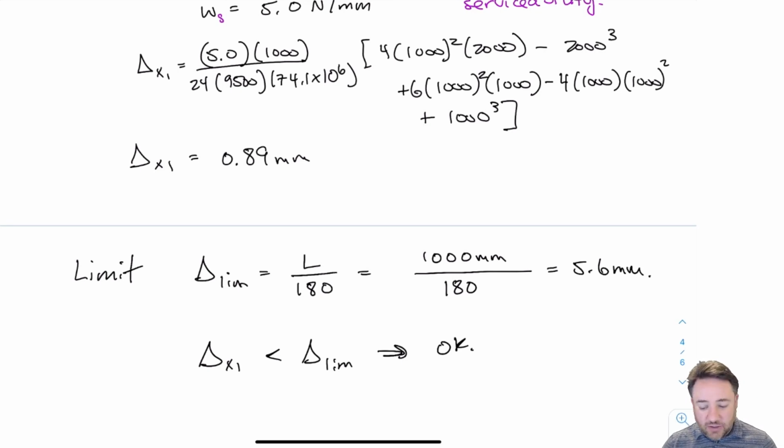So I'm fine. Okay, so in this problem, I looked at a sample lumber beam design. We calculated our size effect, we calculated our S, we found our strength, we looked at our unit strength, we looked at KL, we had to calculate KL for 2 different spans. We potentially would have had to calculate MR for 2 different spans, but we didn't in this case just because MF, the factored load on each span, was the same. I found the limiting MR, and then we compared it to MF, and we made sure that our resistance, including accounting for lateral torsional buckling, was greater than our factored moment, which it was.